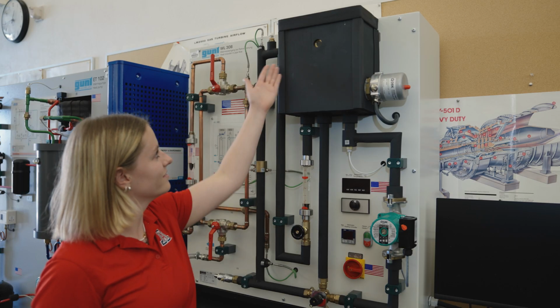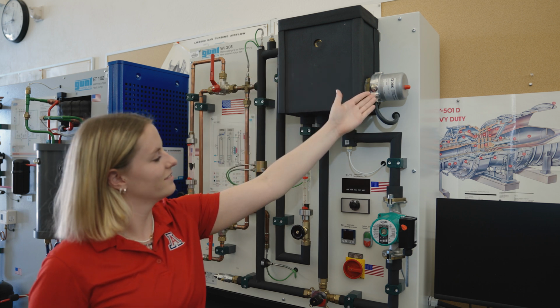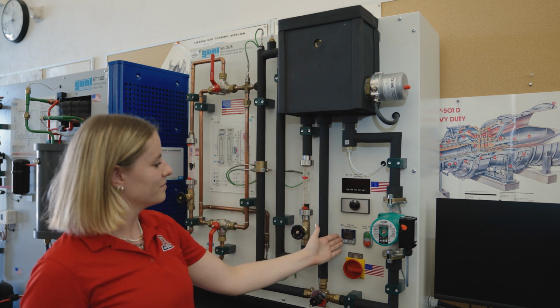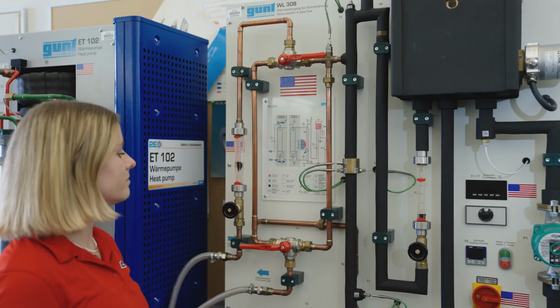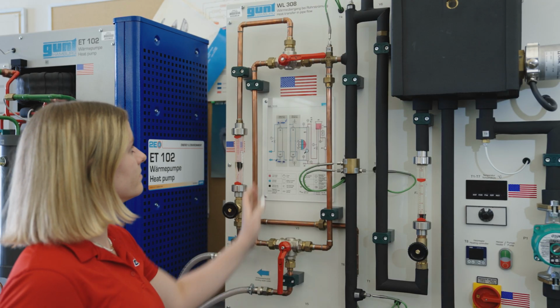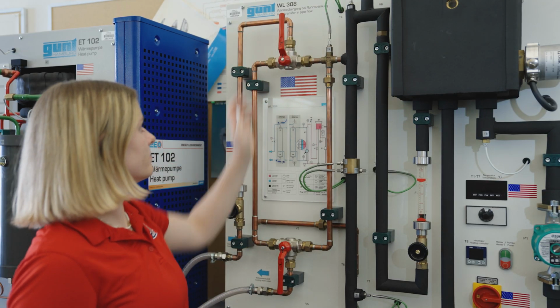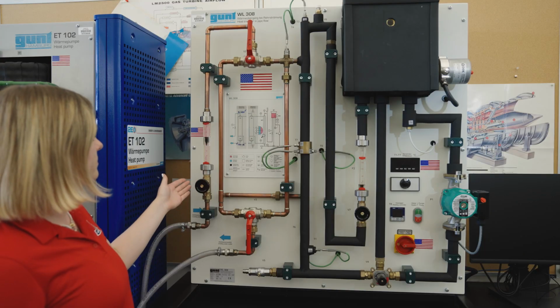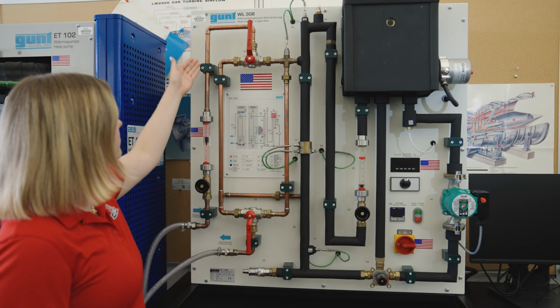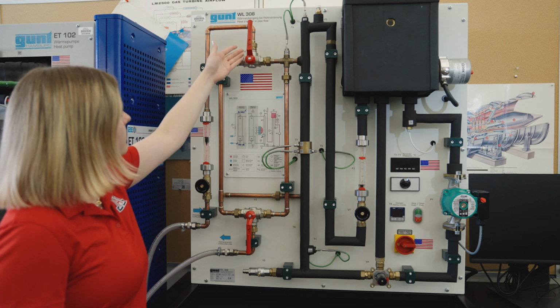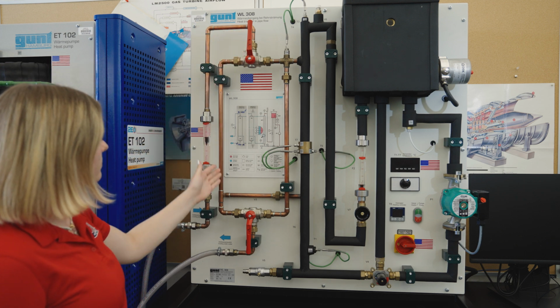The hot water tank contains an electric heater that raises the temperature of the water to the value set by the user on the temperature controller. The water temperature can be adjusted by the temperature controller to a maximum temperature of 60 degrees Celsius. There are two three-way valves that define the heat transfer configuration or operating mode. These valves change the flow direction of the cold water. When the valve handles are in vertical and anti-parallel position, the heat exchanger operates in parallel configuration.